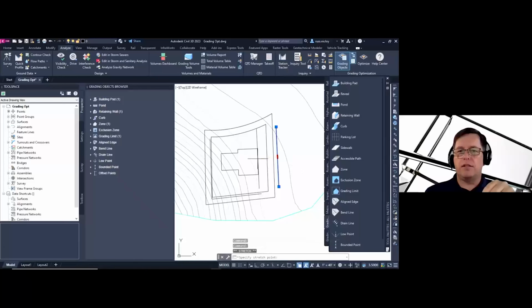If I was to draw this line inside of that area here, the triangles to the west will all point to the line, but the triangles to the east will also point back towards the line and effectively create a ditch. So that's one thing that I had to learn very early on, that if you move this outside of the extents or outside the areas that are grading, it actually gives you a nice gentle slope through an area without having to create a ditch in your design.